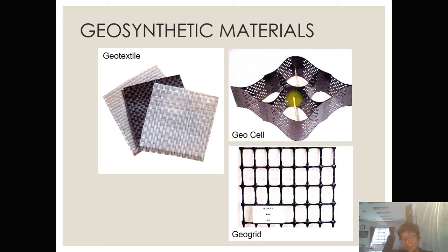It is important to have coverage for the geocell. Why? Because it is essentially plastic, geosynthetic. Plastic doesn't like what? UV. If you're exposed to the sun, very soon this will go kaput and break apart. Okay? And down here, we have what we call the geogrid. Geogrid was actually the focus of Dr. Lok's talk last week.